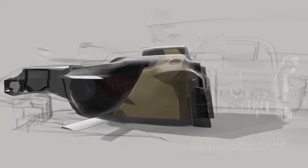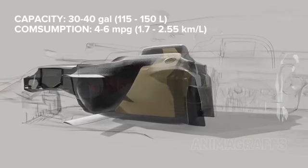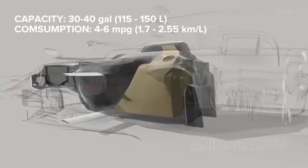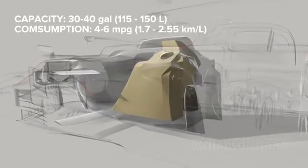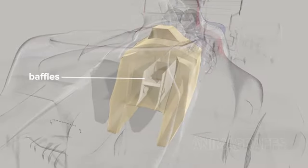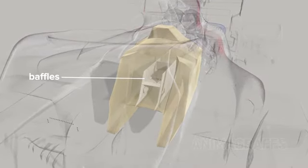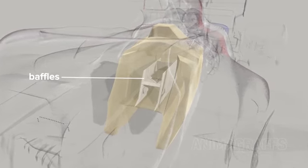F1 fuel cells can hold an incredible 30 to 40 gallons of fuel, which is just enough for a single race, as pit stop refueling is not allowed. These cars get an estimated 4 to 6 miles per gallon of fuel. The tank has various internal baffles with one-way valves to tame the sloshing liquid under incredible racing forces. The goal is to keep the large fuel mass centered and low, and also to prevent foaming and fuel pump starvation.